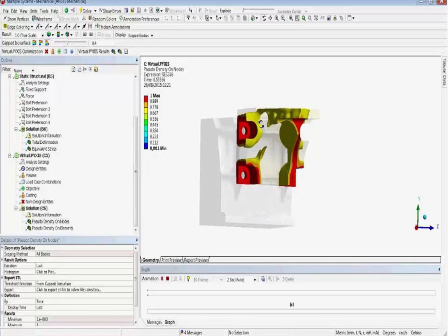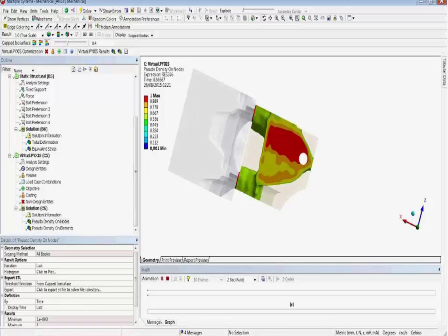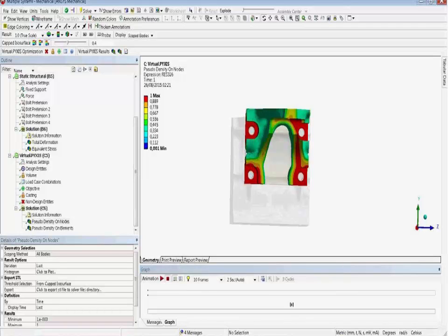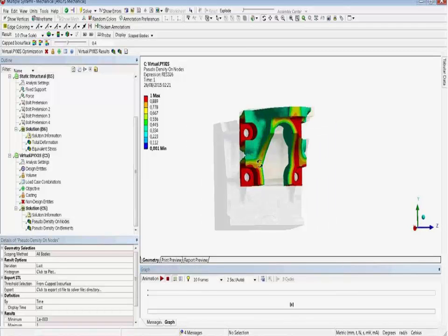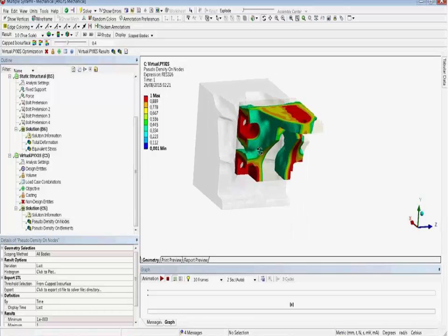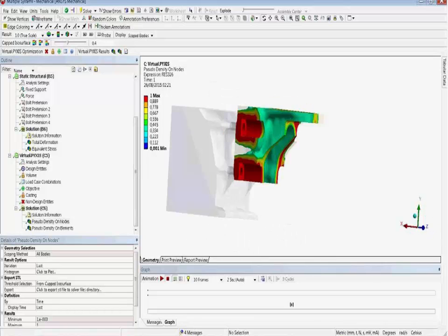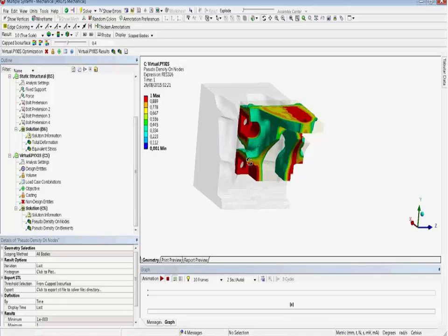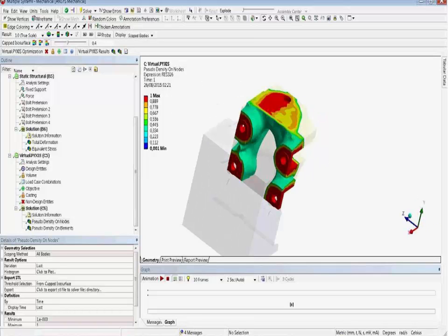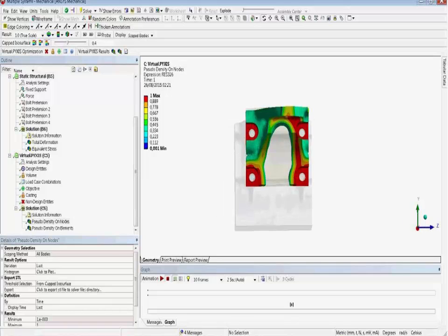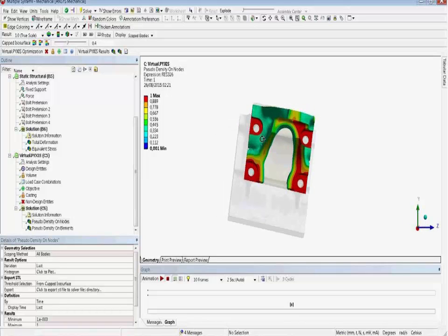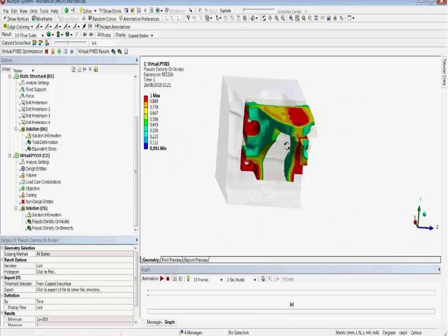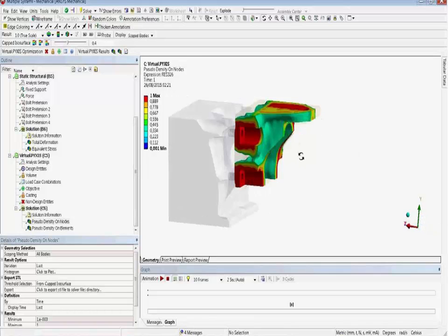For example, you start with a very big extended design, and at the end the software tries to place the material, for example creating these ribs here, in a better way, and most of the time much better than an expert designer or engineer can create. Also you see here there was a manufacturing constraint, so you can use this without any problem to manufacture your model.